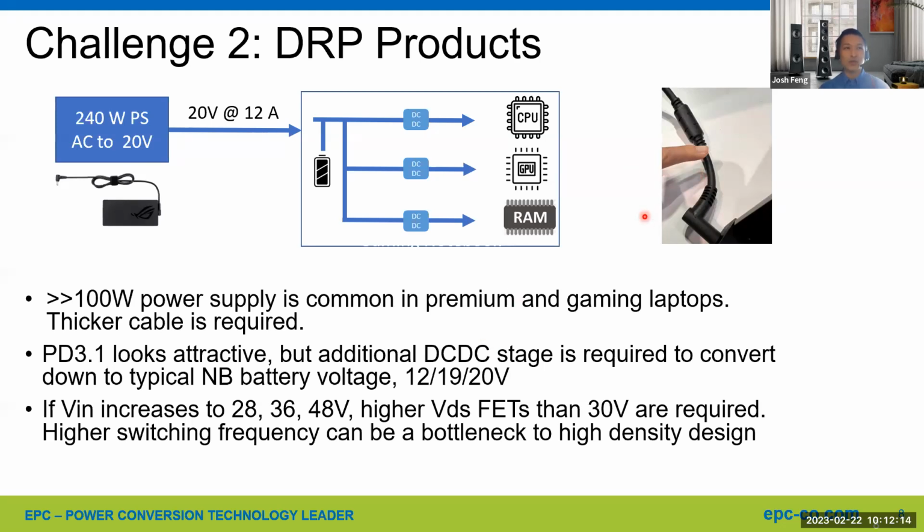I've seen many really cool gaming laptops. But one thing they have in common, they have pretty thick cables. Those cables are not a standard 5 amp cable, I believe. For example, take a 250 watt example: at 20 volt output, you will need 12 amps. Those are most likely specialized cables, and that will run higher cost and a bigger power supply brick.